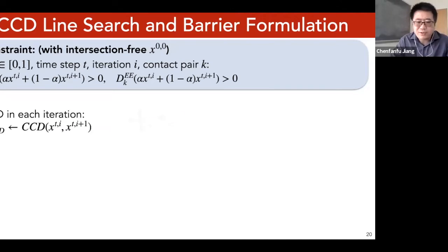for each iteration i in the nonlinear optimization, the configuration update, we can imagine it's a linear trajectory from x_i to x_{i+1}. And we can conduct this computation called continuous collision detection, or CCD. Basically, CCD is a small routine to find the smallest step size, alpha CCD here, the smallest ratio of this trajectory, so that it first brings any distance to 0. So for example, in this drawing, if the red point is crossing this green edge along this trajectory, then CCD will return something like 1/3. That's the first time they will actually collide.